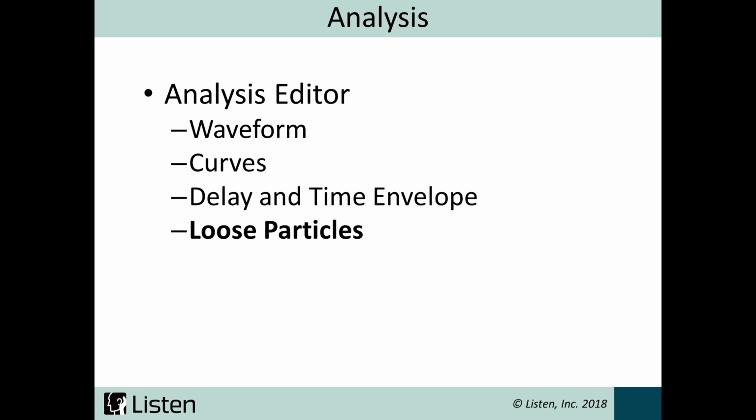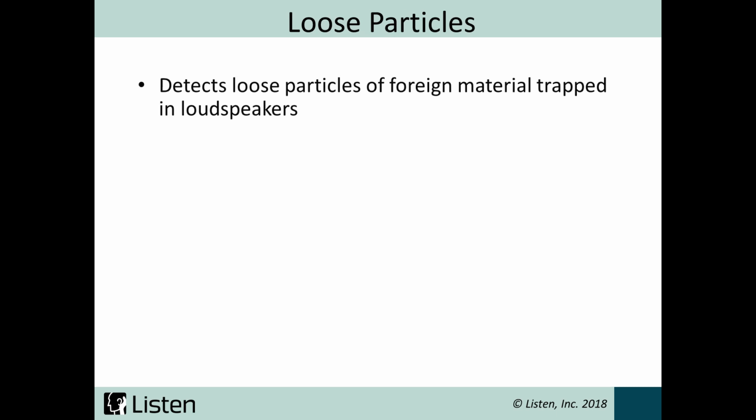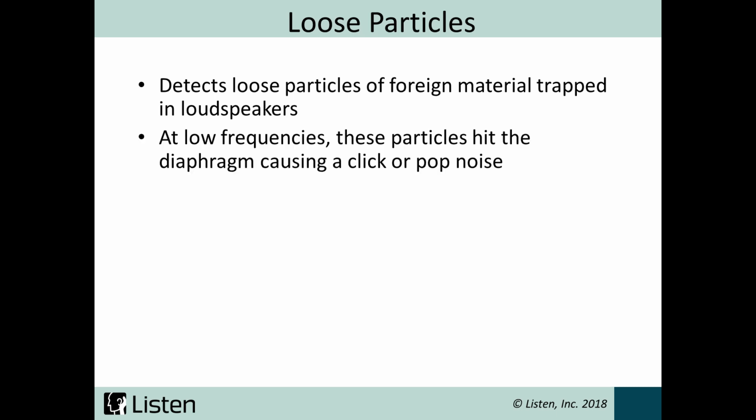Now, let's take a look at the Loose Particles tab. During the manufacturing process of a loudspeaker, some loose particles of foreign material may stay trapped in the gap behind the diaphragm or dust cap. During operation at low frequencies, these particles randomly hit the diaphragm, making a click or pop noise.